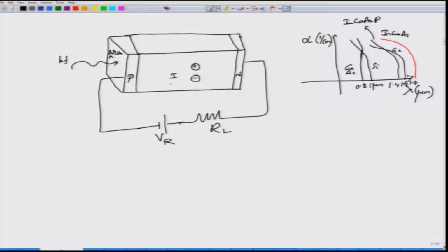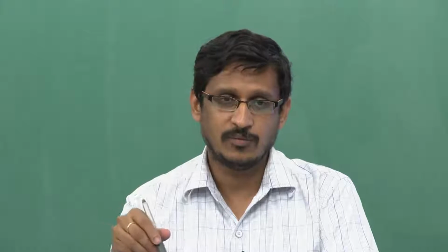Now, if you just refresh the terminology of semiconductors, P stands for p-type semiconductor. The intrinsic one is the one where you have an equal number of holes and electrons, therefore there is no net charge out there, whereas P is the one which has been doped with materials called acceptor ions. If silicon is the material which you have doped, then 3 of the silicon valence electrons are satisfied, and then there would be one hole that is remaining.